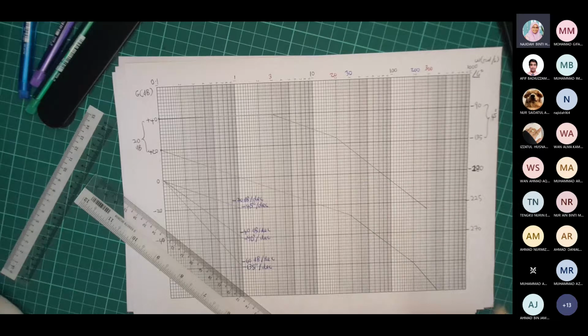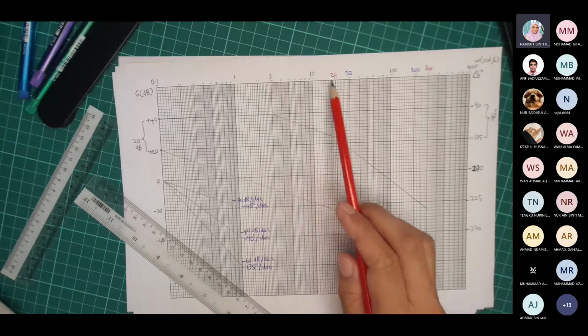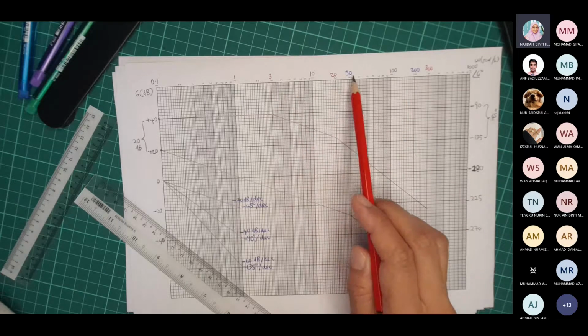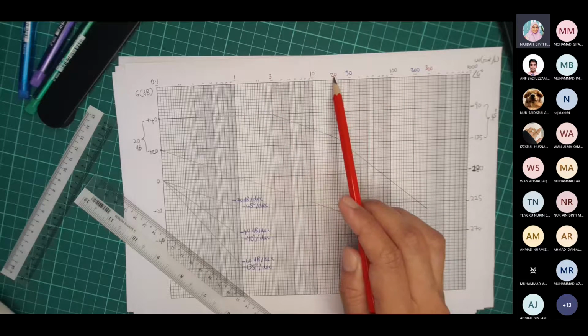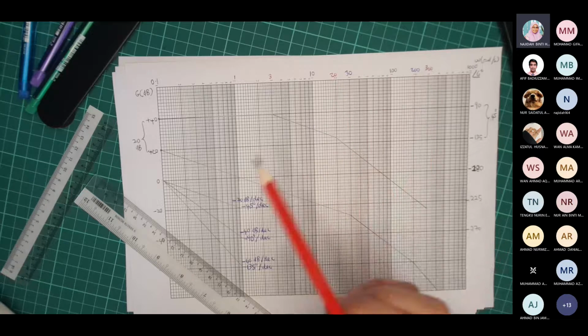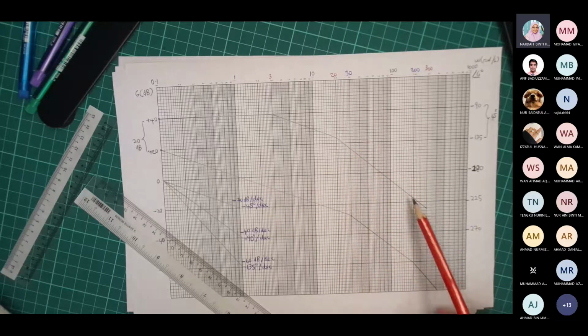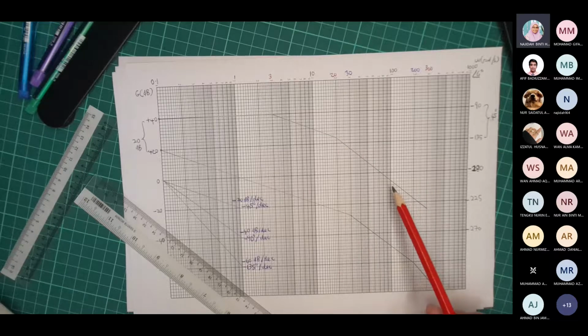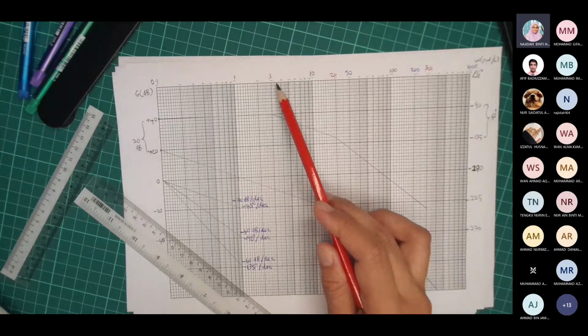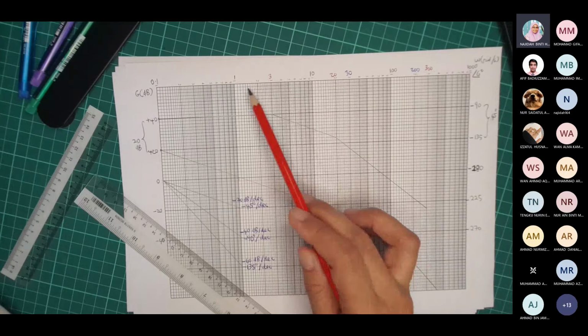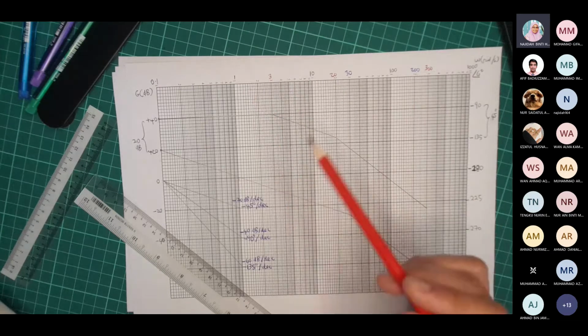Okay, this is why you need to label your x-axis scaling with your cutoff frequencies from the magnitude table, and your minimum and maximum frequency range from the phase table, so that you won't start and stop the plotting of your slope at the wrong range of different decades of frequency scaling on the x-axis.